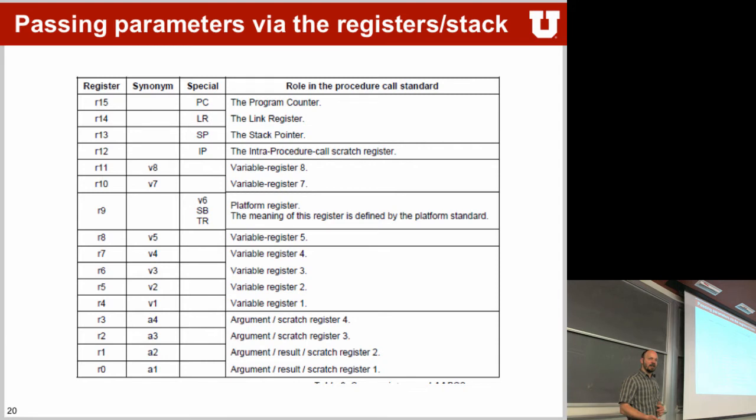So there's actually another way of doing it in the ARM ABI, and that is putting stuff through registers, right? The ABI defines 4 registers as input variables that you can use: R0, R1, R2, and R3. These are arguments that you give into the function, and the function can use them as scratch registers, so it does not have to save them. These registers are expected to not be the same anymore once you're done with your function. All the other registers, R4 through R11, have to be put back into the state that you found them in. So how could you do that?